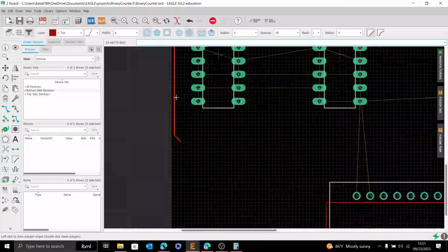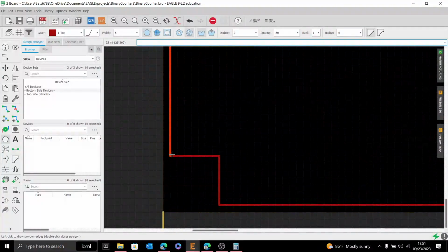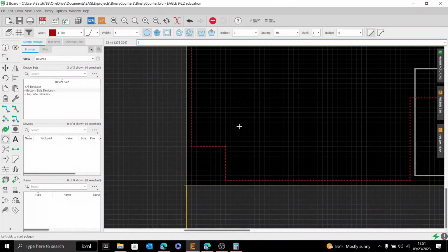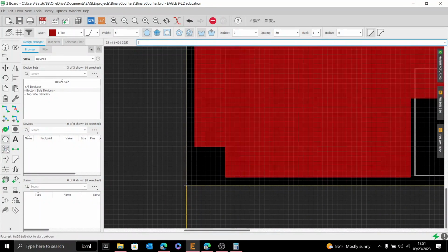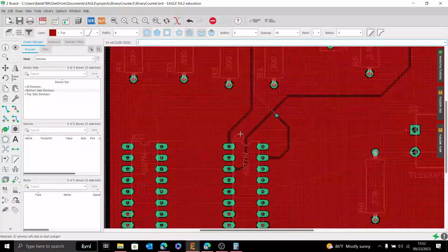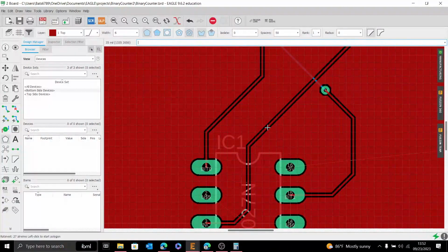So we're going to come all the way down here and attach it up. And this is ground. Now all we have to do is click this little rat's nest, and there you go. You've got a full-blown ground plane. And notice how it even leaves the spacing for the traces. See that?